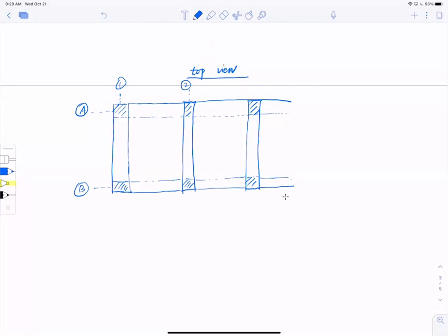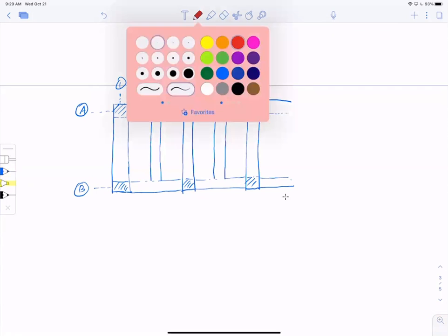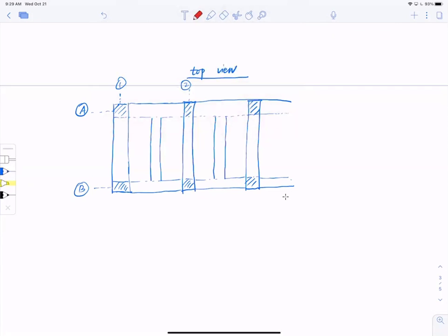I'll have to tell you what the one-way direction is. But AB and 1, 2 seem almost the same length, so I'll add small beams in the middle to shorten it. Why is that? Because now I have a span length from this beam to the center of this beam right here. This is called L1.